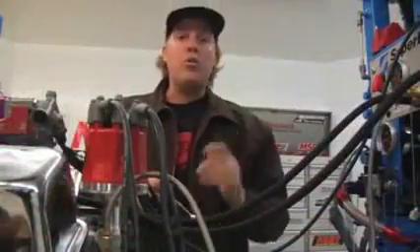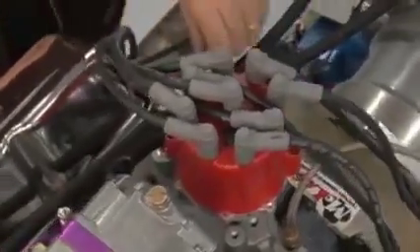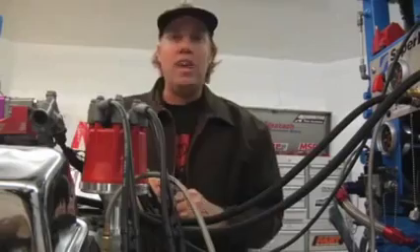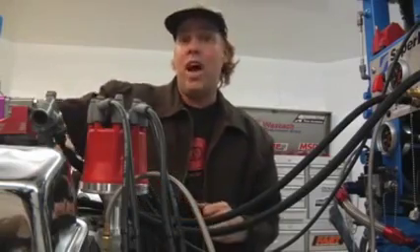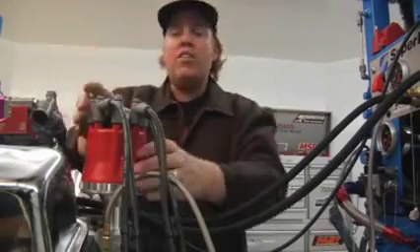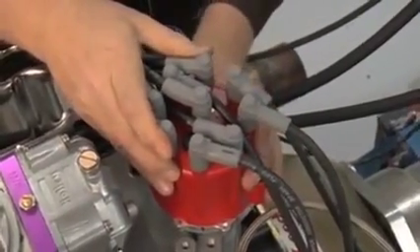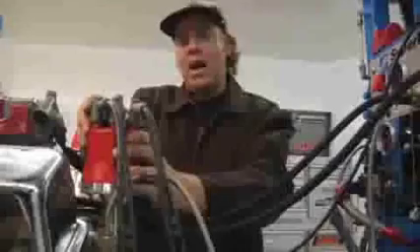We just showed you how to read timing, now I'm going to tell you how to adjust it. First thing you need to do is loosen the bolt that holds your distributor hold down clamp so that you can rotate the distributor housing. Now on this Chevy, where the rotor turns clockwise, you would advance the timing by turning the distributor counterclockwise, or retard the timing by turning it clockwise.